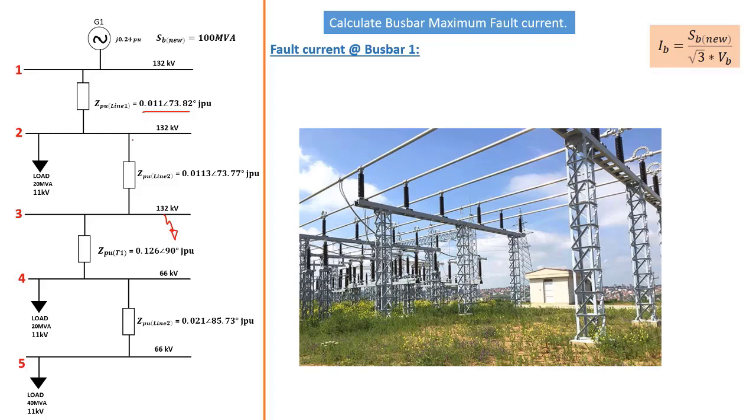This is why we're going to use it to determine our fault current that's going to be flowing to busbar 2. But before, the fault current at busbar 1 will solely depend on what the generator is supplying. Now the generator here, I've explained it already on the previous tutorial. The 0.24 is like an internal impedance, an internal resistance of either the battery or any power supplying device.